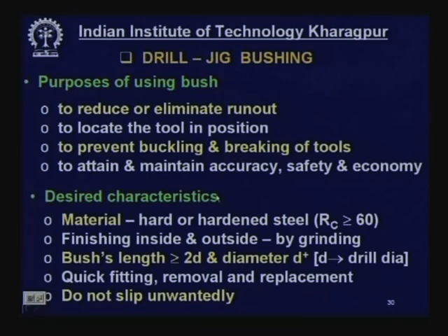Desired characteristics of these bushes: the material should be hard or it should be hardened at the mating surfaces, RC should be above 60. Finishing inside should be by grinding and lapping, outside by grinding, because it plays a very important role in finishing accuracy. Bush's length: